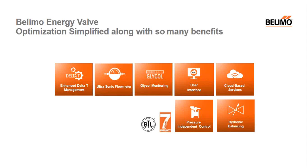So to summarize here, I talk about optimization simplified along with so many benefits. We talked about the Delta T Manager and the options that we have there for helping understand the Delta T. We can use the data analysis tool for one. We can use our Belimo Cloud to help understand what the best Delta T set point is. We can use Belimo ClearEdge. We talked about how that Delta T management really helps save pumping energy. So there's a lot of pumping efficiency to be achieved by optimizing and eliminating that low Delta T. We talked about the flow meter and the ability to measure glycol.